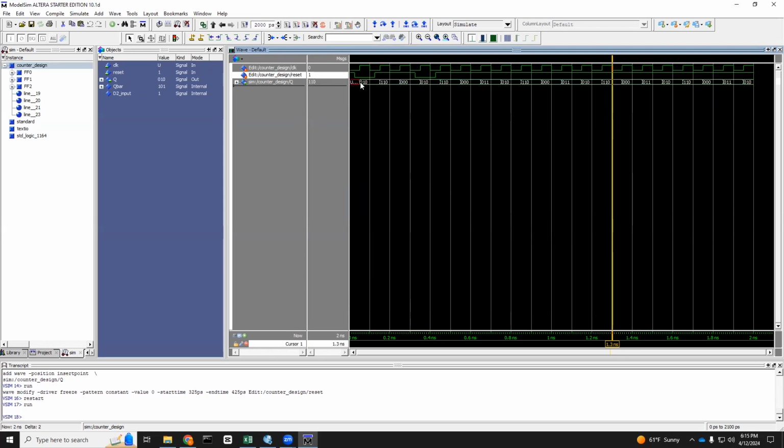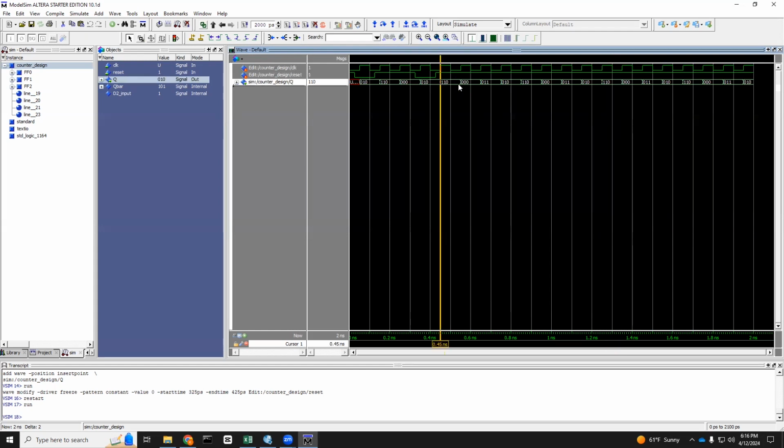Okay, so your initial sequence for your first reset has gone to 010. You get a clock pulse, 110. You get another clock pulse, you go to 000. Now for the next clock pulse, my reset is 0, so my sequence is reset, which means I go back to 010. Again, reset goes high for the next clock pulse, and the sequence starts counting. So you go from 010 to 110, followed by 000, followed by 011, and then it repeats all over again.